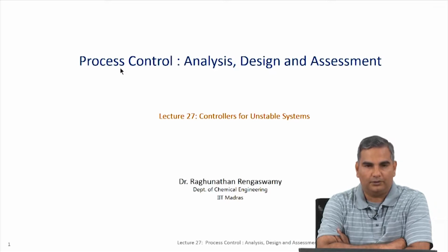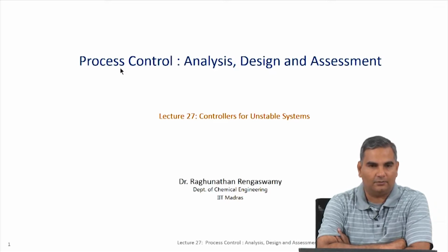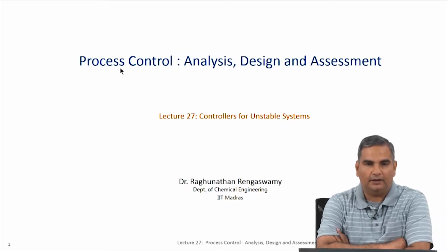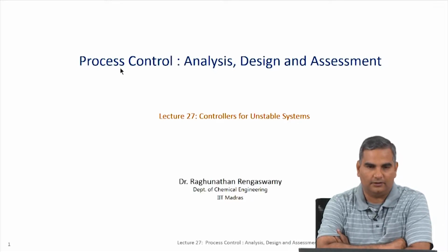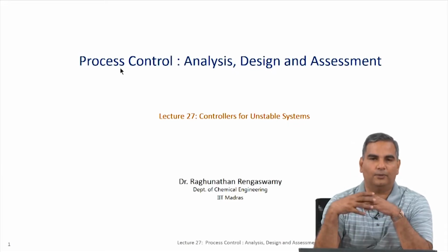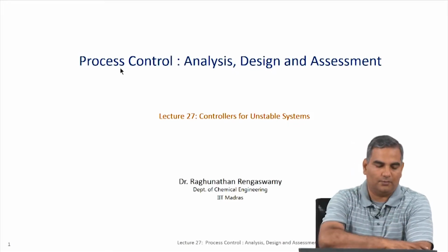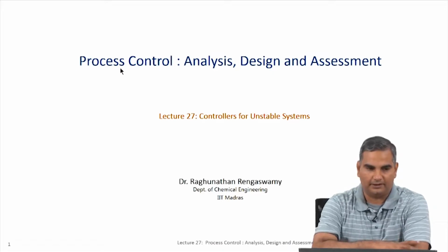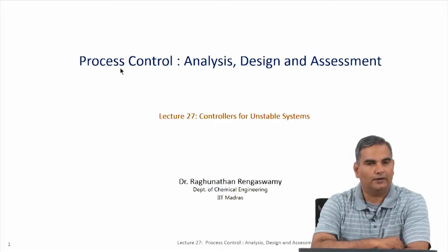And we followed that up with control of time delay systems, talked about the difficulties in getting the controller in terms of getting a realizable controller. And then I showed how the direct synthesis approach could be used to design the controller, and while we implement the controller, we also see that you have to use the model during the implementation of the controller also. And I said as we go forward, you will see more and more of the use of model directly in controller implementation. Nonetheless, we saw how we could get reasonable performance with closed loop control when you have inverse response